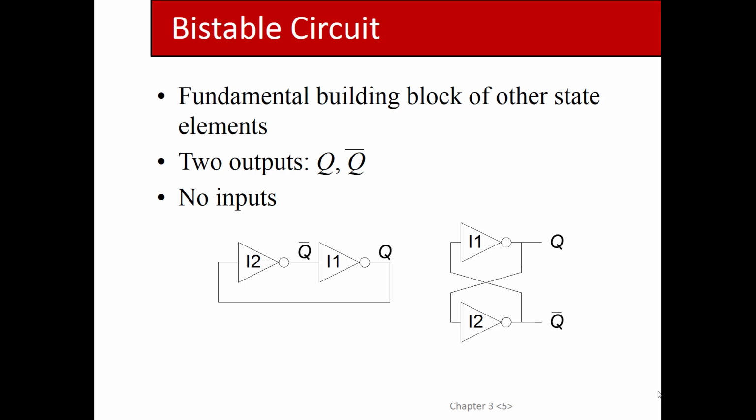If you're doing combinational logic design, you never want to do this; your circuit should be acyclical. But in a sequential logic element, notice that this inverter comes out, goes into that inverter, which comes out and goes back into this inverter, and there's this infinite loop in there. There's a cycle.